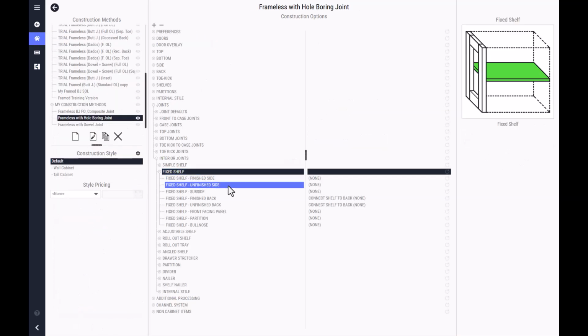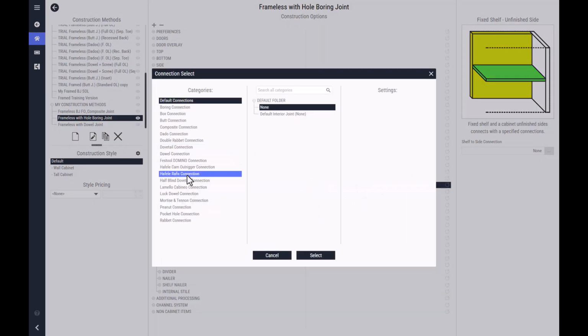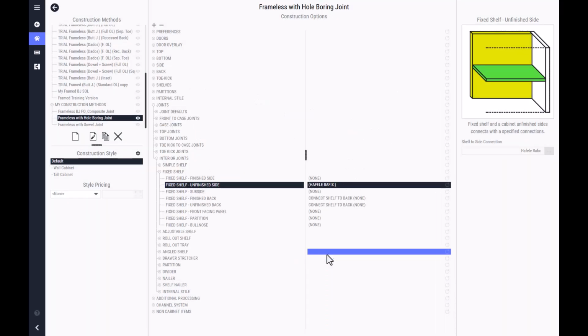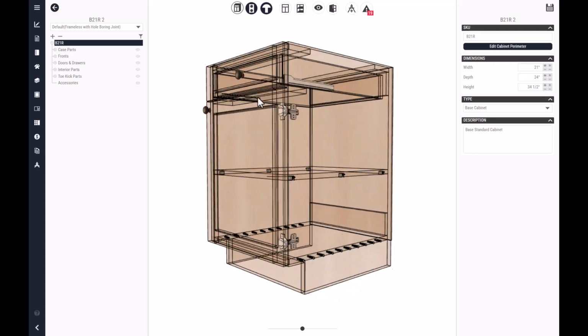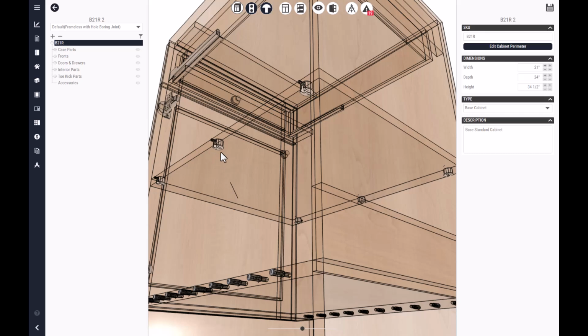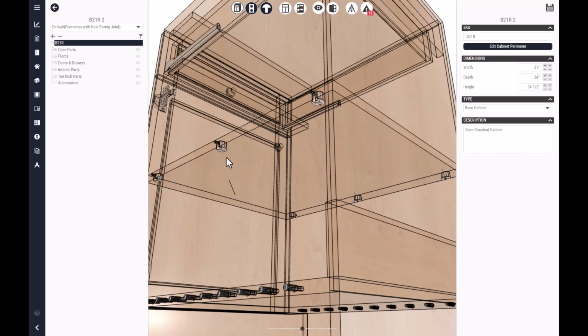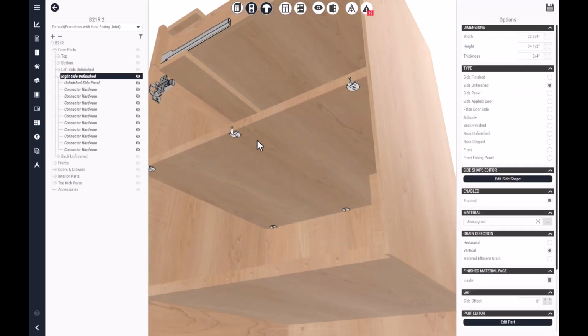Apply the Rafix or CAM Outrigger connection construction to the desired joints within your cabinet construction method. Then we will generate a test cabinet, open the wireframe, and turn on Show Processing. Verify the main connector pockets, additional outrigger pocket, screw holes, quantity, spacing, placement, and mounting side. The dimensions supplied by the default templates are starting values. Before changing those dimensions, compare them with the drilling specifications for the exact connector your shop is using.